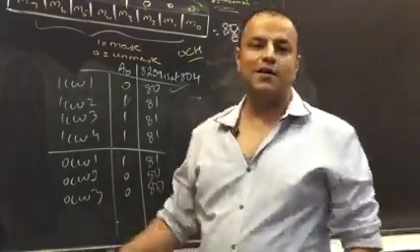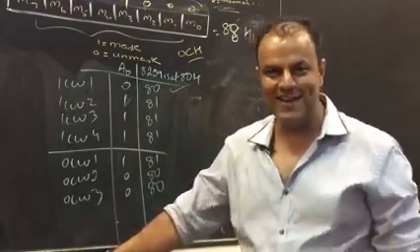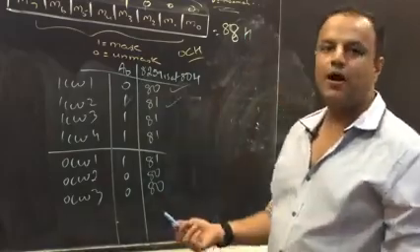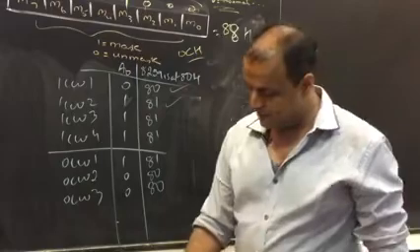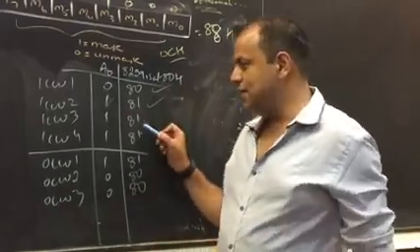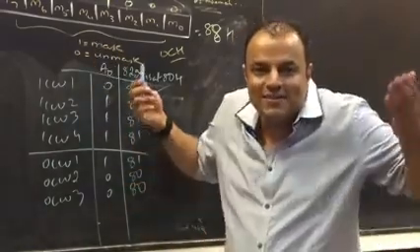Now the first command that comes to you at the address 81, which one is it? Has to be ICW2. How? There are 4 candidates at 81. I agree. And OCW can never come before an ICW. ICW 3 and 4 cannot come before ICW2. They have to be given in this order, and ICW2 is compulsory.